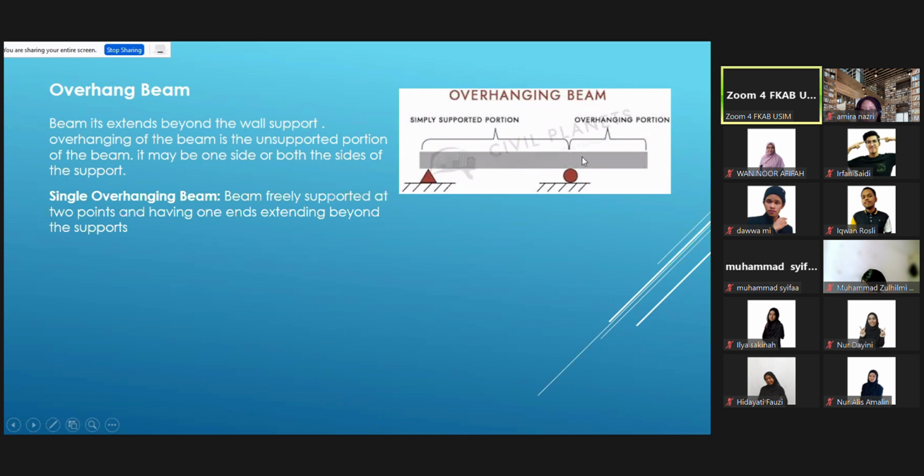In this case, it is like an overhang beam. There is some kind of counterbalance element at the back. That means this beam is being tied to the support behind, to feel the support behind. And then it will be much stronger. The reaction here is very strong. They keep it stabilized because of the anchoring here. So it's a beam that stands beyond the wall support.